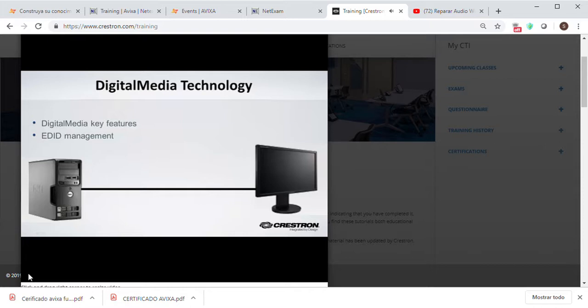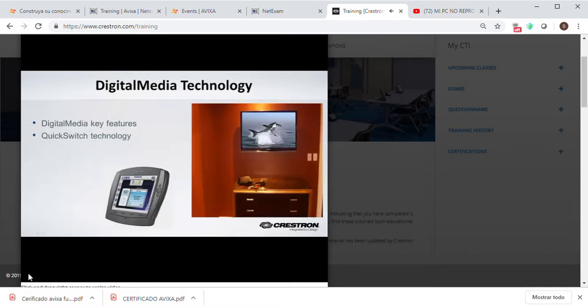However, serious conflicts can arise in a facility filled with different displays and audio systems. Resolving this confusion in the systems that have multiple syncs using EDID becomes vital. Digital Media manages EDID to prevent such conflicts, assessing the format supported by each system device, and then allowing the installer to assign compatible devices in logical arrangements. Conflicting combinations can be prohibited, so only the optimum signal formats get delivered to each display and audio system.